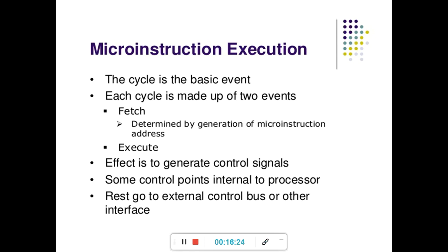The execution includes the sequencer for controlling the sequential readout of microinstructions from a read-only memory for storage in the microinstruction register and for subsequent decoding by a decoder.